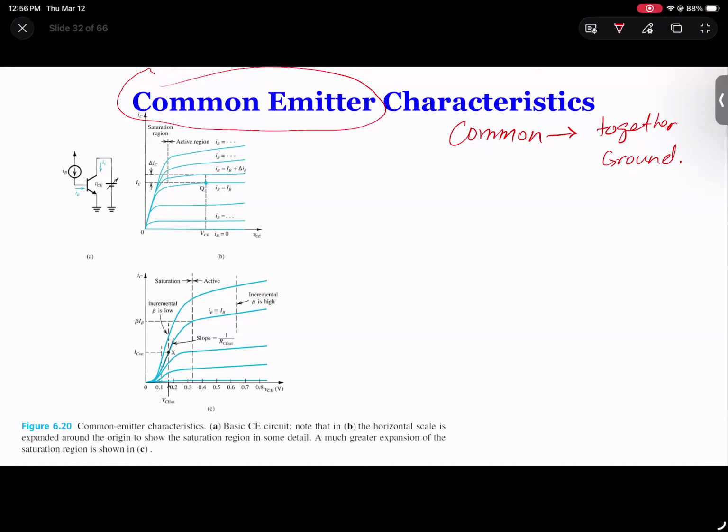When you were in the lab using the oscilloscope, you remember you have buttons where you select AC, DC only, or AC only, or both together. When you push that button, it measures everything, including DC and AC, but when you press AC only, it filters out the DC and only displays AC. So this is what happens in your future.